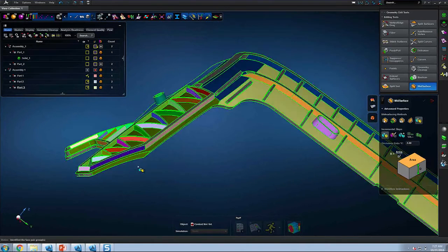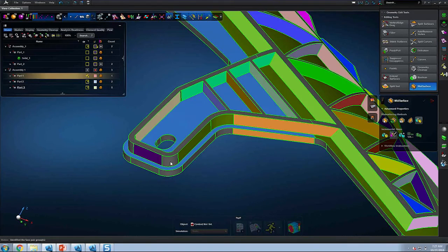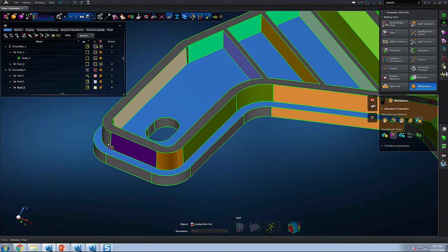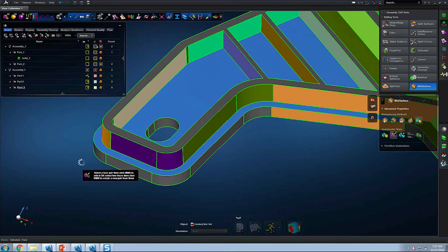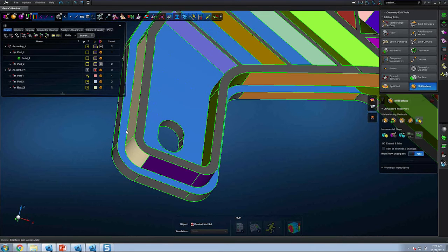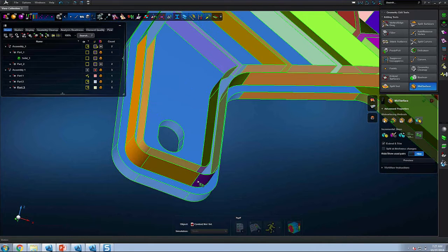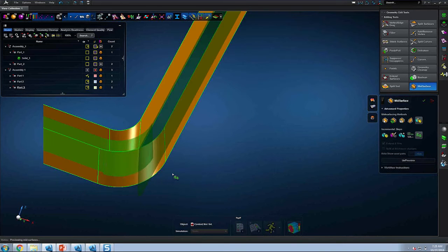Let's reorient the model. And like before, we'll create some pairs here at the rounded edges of the perimeter. And now when I view a preview of this new midsurface that I've just created, you'll find that now we have a curved appearance in the midsurface geometry.